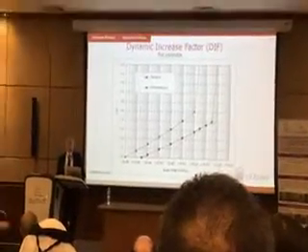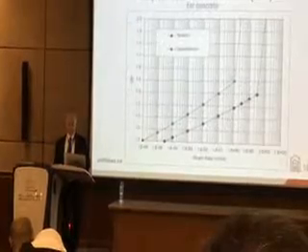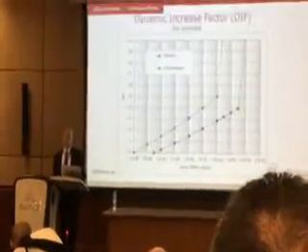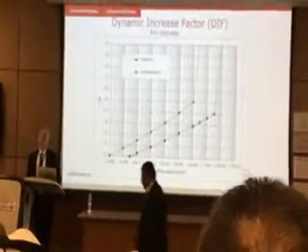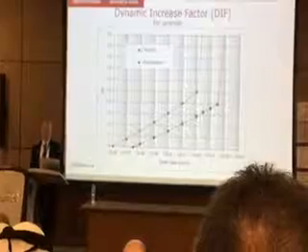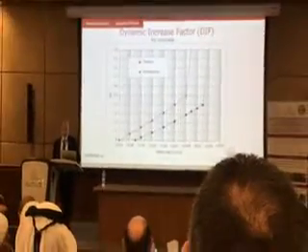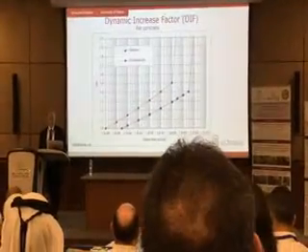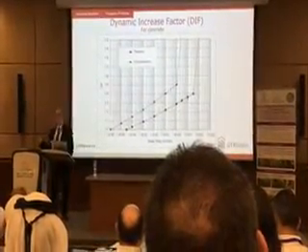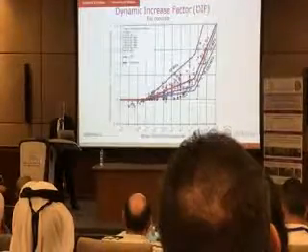In fact, here it shows concrete tensile capacity and concrete compressive capacity. We're talking about 30%, 40%, 50% increase. Significant increase if strain rate is very high. Usually, this is the blast strain rate, this is the impact rate, and this is the earthquake rate. So during earthquakes, the dynamic increase factor is about 1, so we ignore that. But for blast, we may consider that.